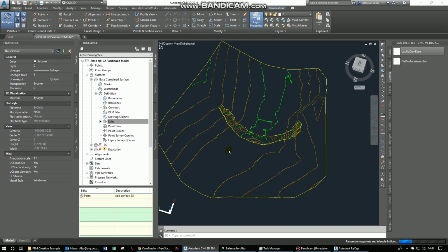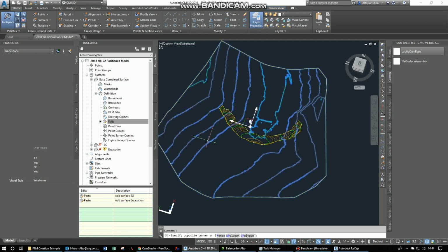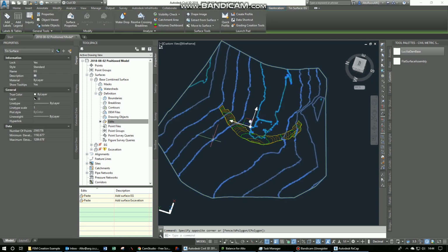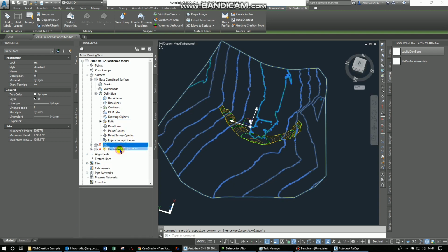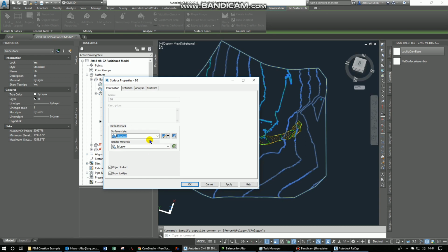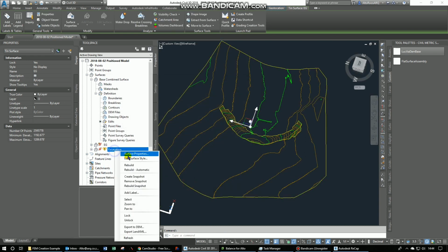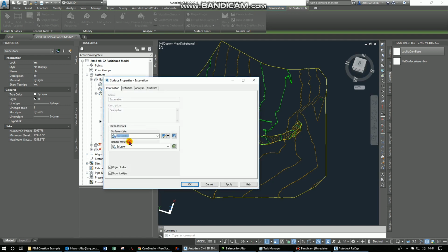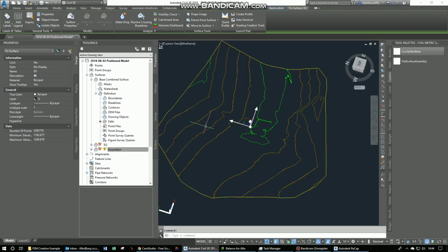So basically what that does is it pastes the one surface on top of the other one, so everything within the boundary of the excavation one will replace the data that we had on the extremely fine point surface. Let me just quickly turn these off so we only look at one of these surfaces now, and then I'll show you how the combined one of the two looks, since you saw the different contours for the individual ones earlier.